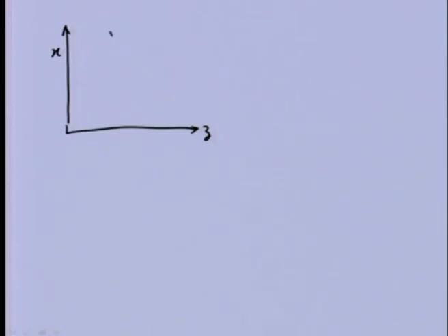If we draw the free body diagram of the disk only, I am taking the tilting in the positive direction. I will show this. So this is the x displacement, the translatory displacement, and there is a tilting which I am taking as positive direction, z to x. I am calling that phi z.